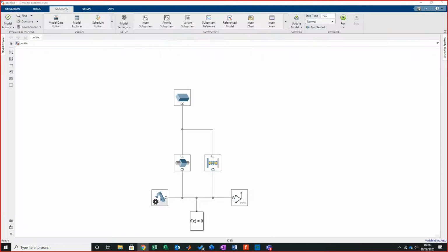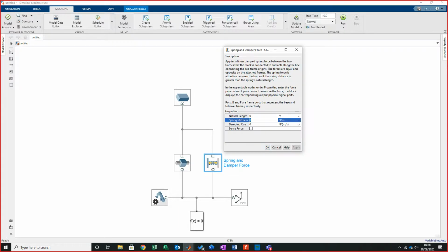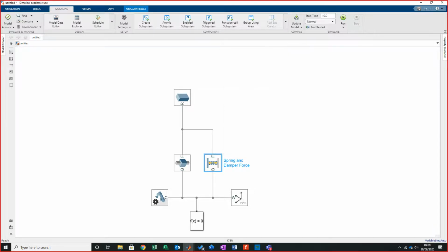Yeah, at least that's what we've not set. I've just thought, we've not set a spring stiffness yet. So let's set a spring stiffness. I'm just making this one up off my mind. Actually, I'll go 50 Newton meters for the spring stiffness, and I'll probably just go 50 Newton meters per second for the damping coefficient. So it's almost balanced completely. If I click apply, then okay.